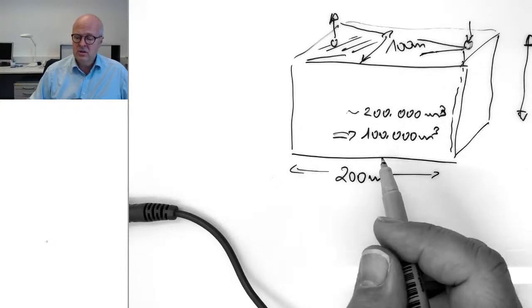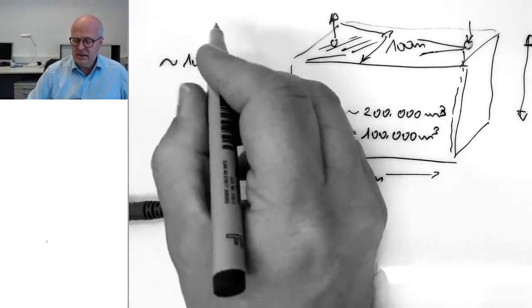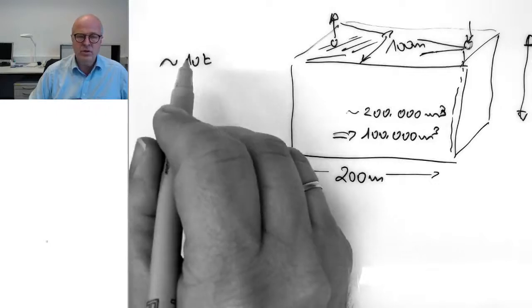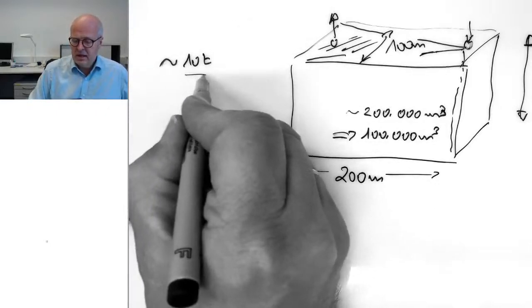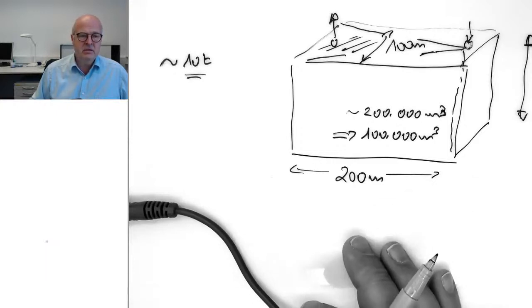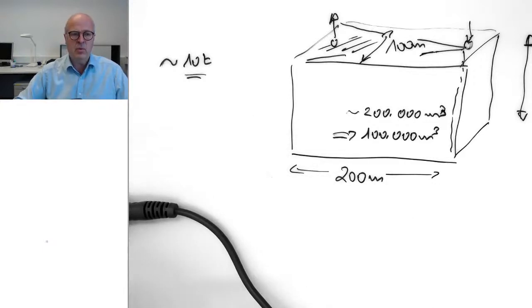And this is a very short distance, so 10 tons. And because we need to include the density of the tracer, which is much higher than the one of water, we talk about several tens of tons. And you see that this is not possible. We would need a truck with salty water injected, and nobody will like this, and it's also a logistic nightmare to do this. You will learn that if we use tracers instead, artificial tracers, fluorescent tracers, we just need milligrams or grams to do the same experiment successfully.